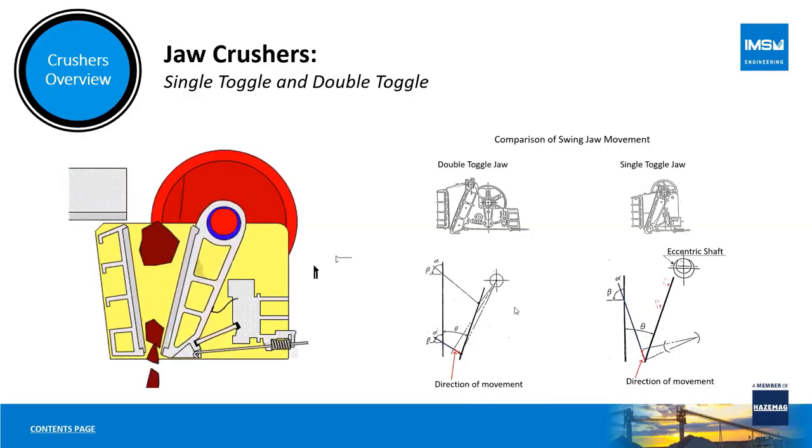First shaft is a pivoting shaft at the top of the crusher, and the second shaft is an eccentric shaft that drives both toggle plates. This creates pure compression, and because of its pure compression with not much attrition, this is generally used for even harder abrasive material than one would normally use it for a single toggle.